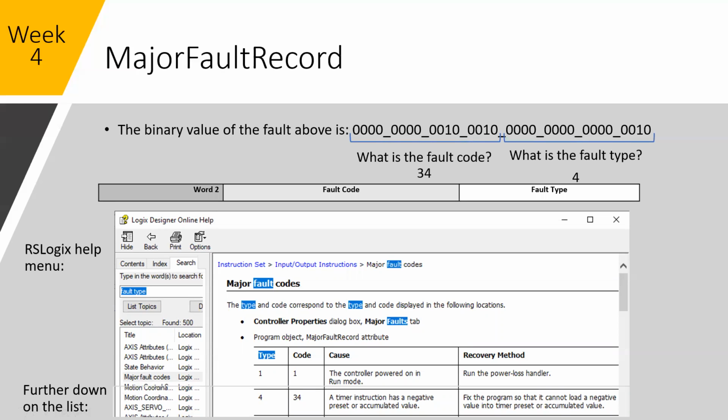Again, if your first interaction with a processor, you're working for an integration company or you're part of maintenance, and they say, hey, this line's down, and you go down there and the processor's faulted, the first thing you're going to need to do is get online with it and figure out, why is it faulted. So all of the information on how to extract the fault code,